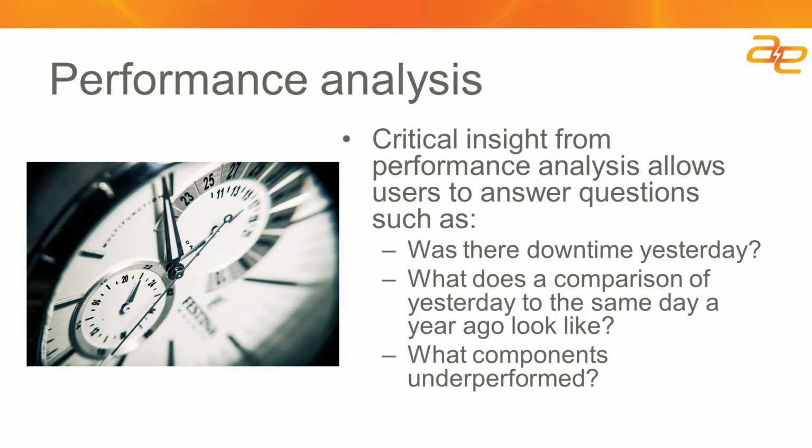It may appear as if you've had a downtime event, but I would recommend that during that time you also compare the output of the site from the site meter to see, in fact, if there was actually some downtime in an event, or if we just lost communications to the inverter. We didn't know what it was doing for a period of time. Communications was restored. The energy from the site is going to tell you the real story. What you get from the inverter might not be perfectly accurate.